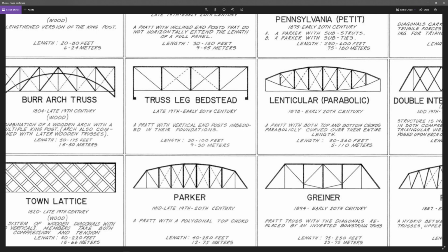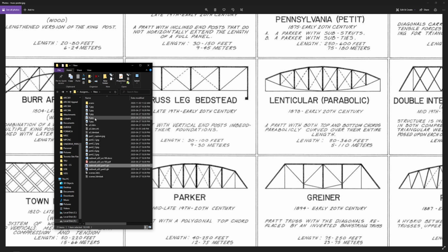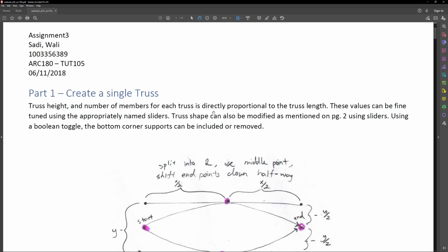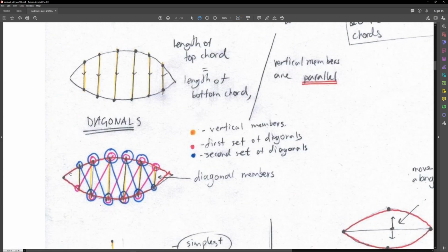And if you look at the diagonals, the points on the top and the points at the bottom for the right diagonals, let's see if I have this open still. This might be useful. Okay. So the points on the top here, we're going to be ignoring this endpoint here. If you remember, there's 2 curves here and each of them are divided up, so there's 2 points here that are overlapping. To create our diagonals, on the top chord, let's create the blue diagonals first. So we ignore the first one, we keep the second, we keep all the rest except the last 2.